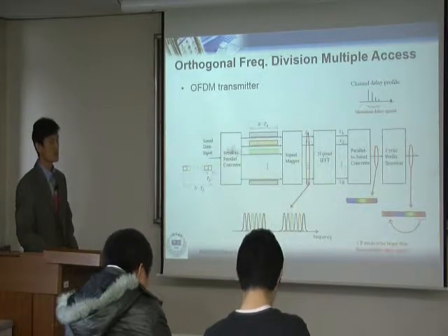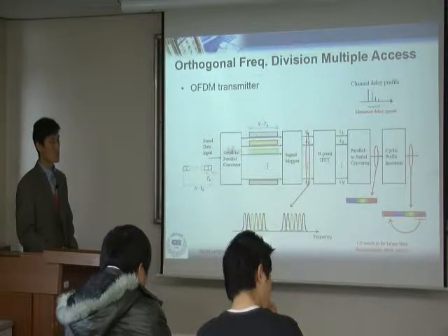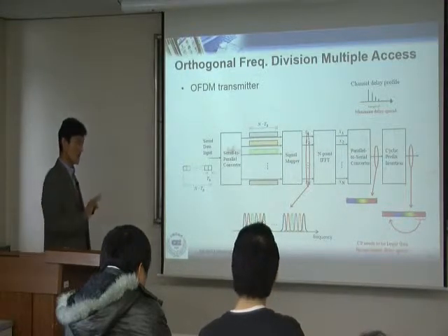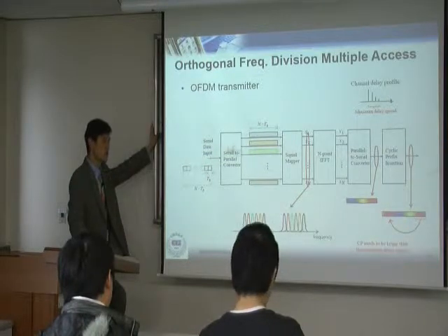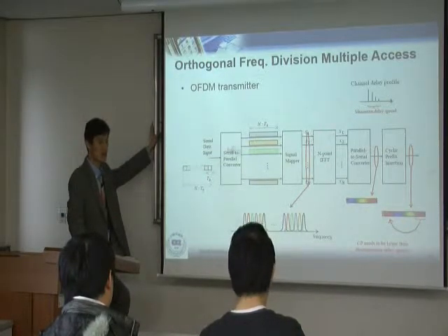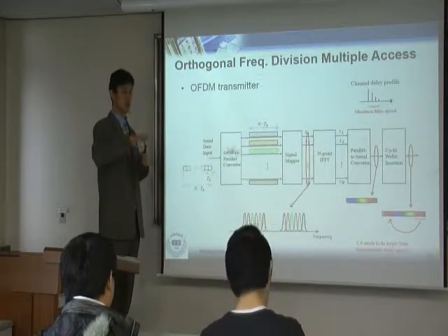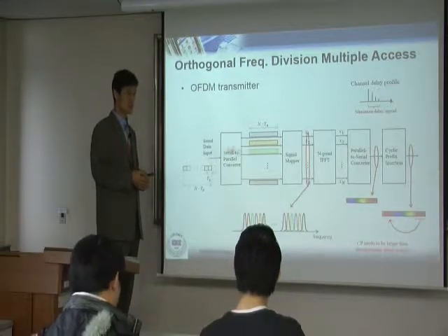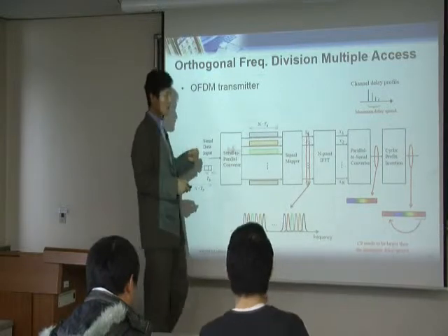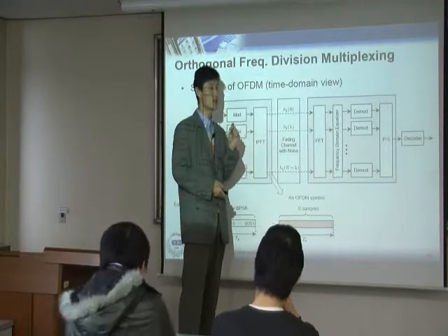One question: if it is frequency flat, we have learned that we don't need an equalizer, if the channel is flat. Exactly, the exact wording is that in frequency flat, you need a one tap equalizer. We typically don't call that an equalizer because multiplying one tap is nothing. We typically call it an equalizer when you have multiple taps and you do equalizer design. But one tap needs no design, it's just one multiplication. So some people simply say we don't need the equalizer in frequency flat. But actually, even multiplying one tap is an equalizer, probably the simplest equalizer.